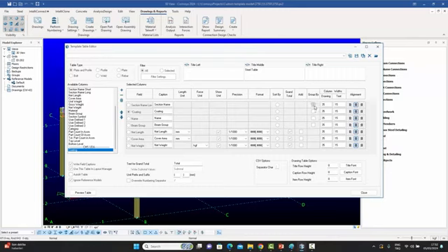So for example, if you wanted to collect all parts having the same section name, you could say group by, and it would group by the section name, and then it would add the net lengths of all those with the same section, or add the cover areas, add the net lengths, and also give you the grand totals. So basically, whatever variables you want to group by will be brought together, and the totals and subtotals will be based according to this grouping.